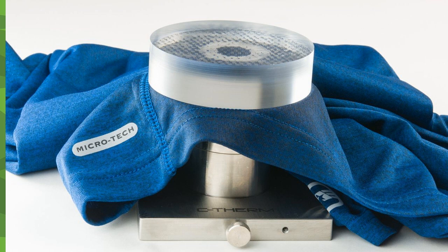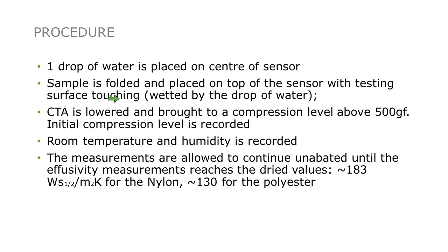It just simplifies things a little bit from the perspective of testing a wetted material where it's already quite dynamic. There's a lot of reasons the CTA is very valuable in dealing with compression, but I think those are more relevant on a dry material than they are necessarily when you start to look at wetted scenarios. You want to make sure that just like under D7984 that we're monitoring the room temperature and the relative humidity of the environment.